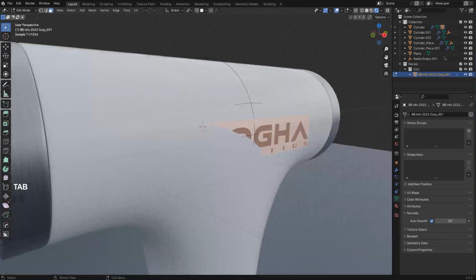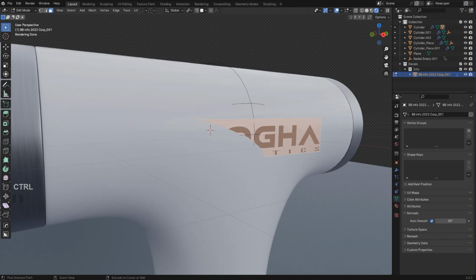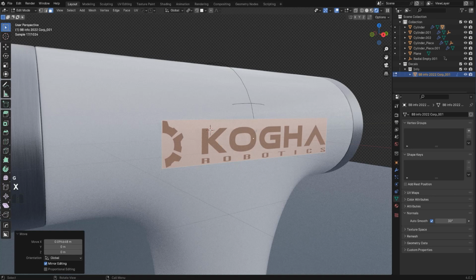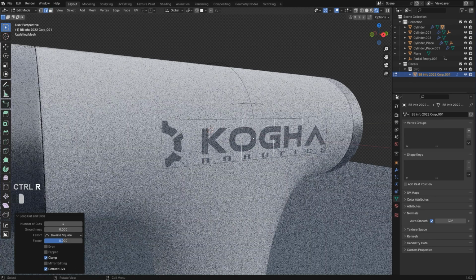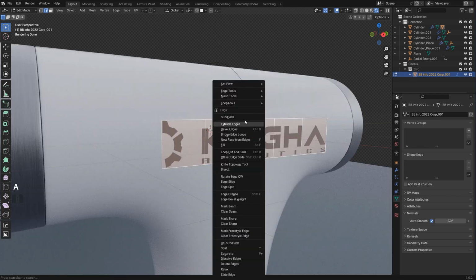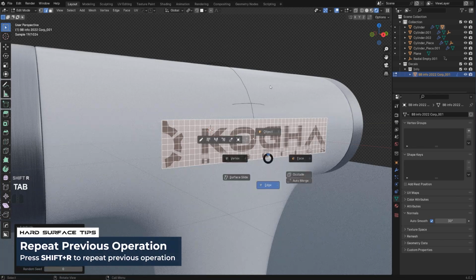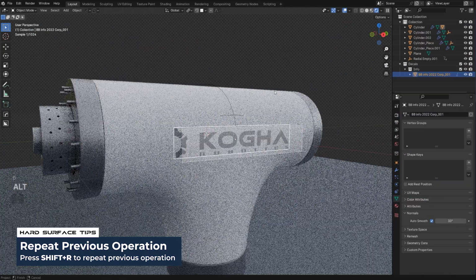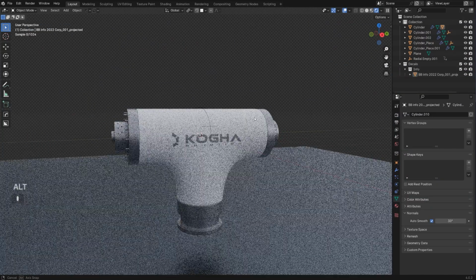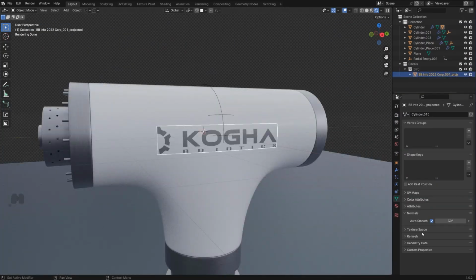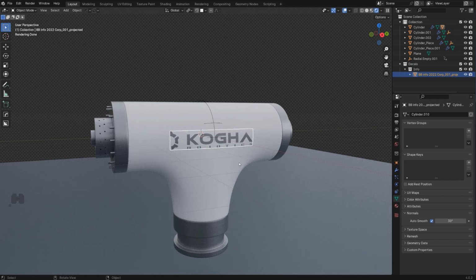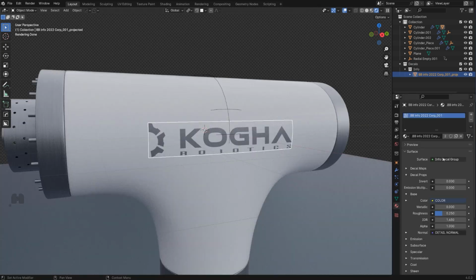This is a curvy surface, so you might want to subdivide this. Subdivide it in here in the quads, select everything, then subdivide, Shift R a few times. It's going to project a bit better, like this. And if you want to change the color, which I don't think we should in this case, but we can, go here. Now the 4.0 has a different setup here.